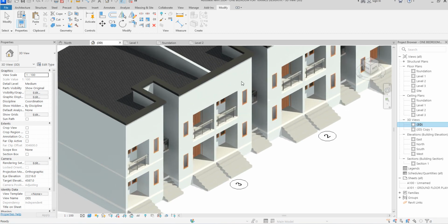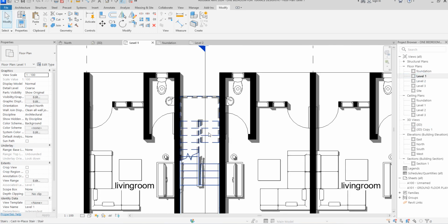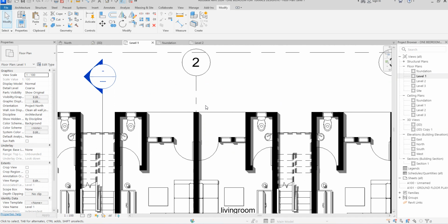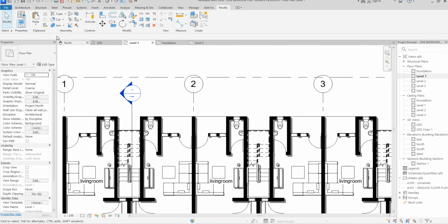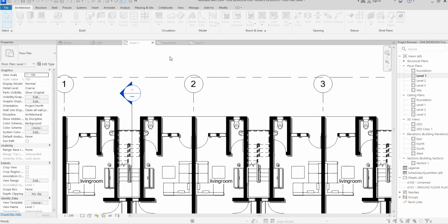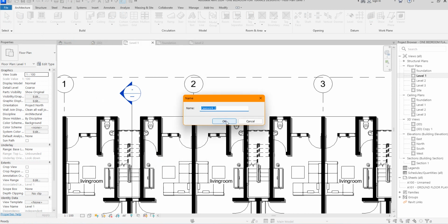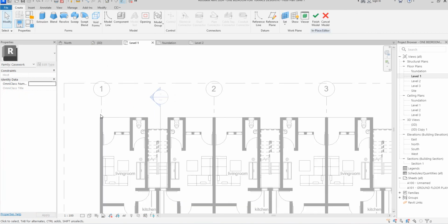So the next thing you need to do is to change the attachments to the wall. So we're going to do that and say level 1. So how do we do it? We can use extrusion, use whatever we want to do. So I'm going to use extrusion in this case. I'm going to click here, say extrusion. So bring model in place and then casework. So creating casework, I'll just leave it for casework. We don't want to attach the wall whatsoever.